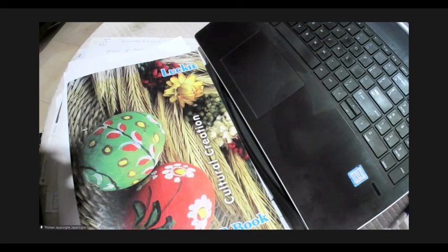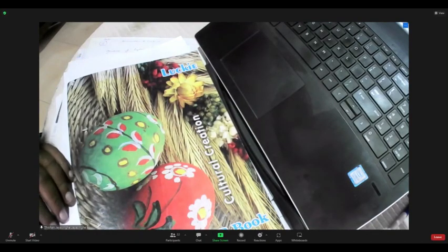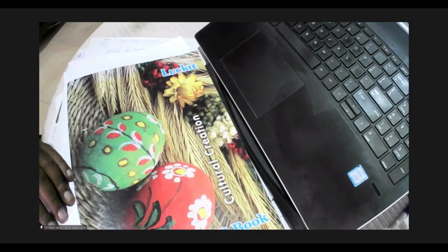What do you think, Bashita? Do you like to stretch materials to that kind of limits? Bashita? You are there. So we can stretch the material. So if you can get 65 megapascal in 24 hours, can you get 90? Yeah, use a little bit of fly ash and allow it to cure for some more time. And by doing little tricks, 80 or 90 is not a big problem. So that is our future.